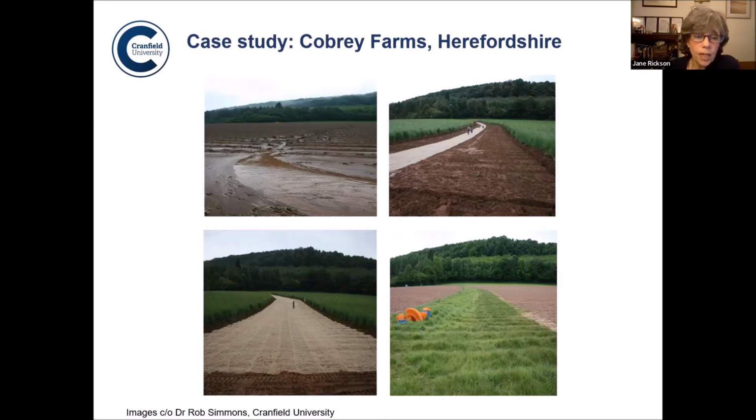This is what the geotextile looks like once it's been laid down, encouraging the grass to grow through that geotextile, so controlling any erosion, any runoff that is coming off the land. The geotextile will do that itself in the short term, but once you've got that grass, you've got this composite control of erosion and runoff, and it works very, very well.